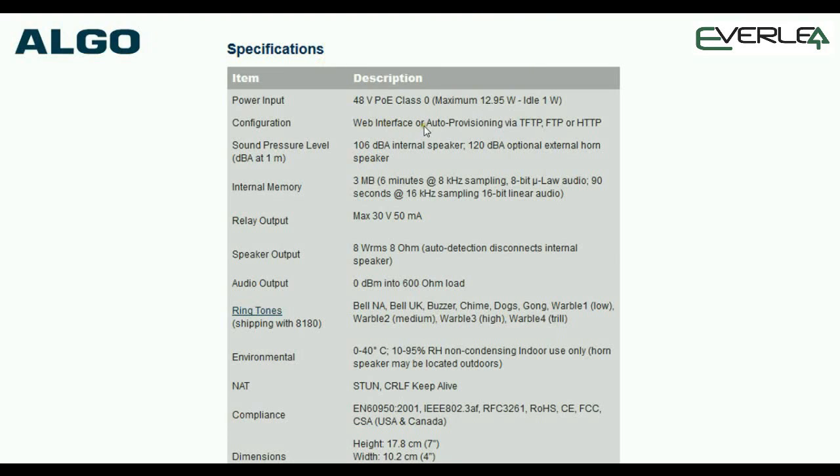Anyway, configuration, web interface, you can auto provision, etc. Talks about the sound. Internal memory is 3 meg for recordings, and you can actually record your own announcements and recordings and ringing and load them up into the unit. The relay, 30 volts, 50 milliamps, speaker output, audio output.